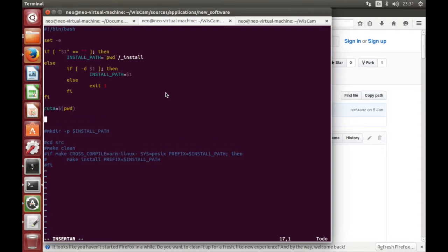If we want to build a program for the ARM processor, we must not use gcc. We need to use arm-linux-gcc, the main path, /main.c, with the output, main path, /test_arm.